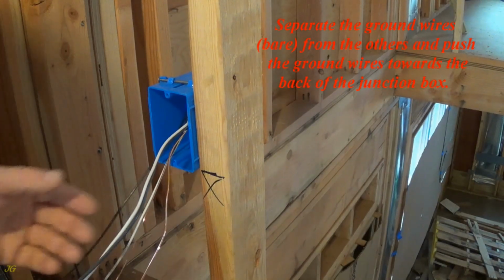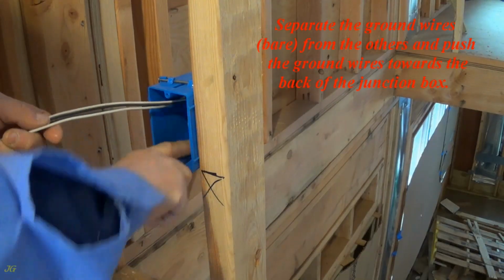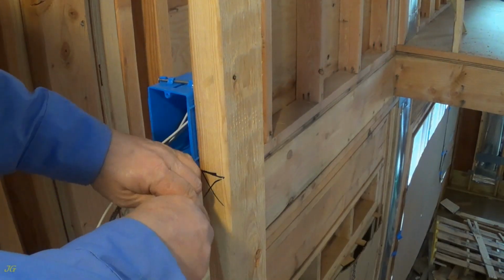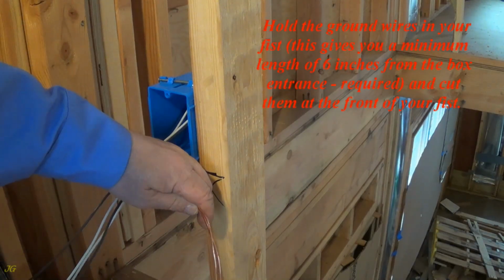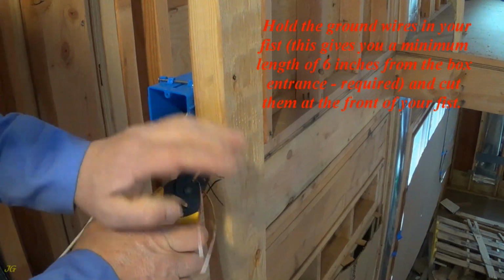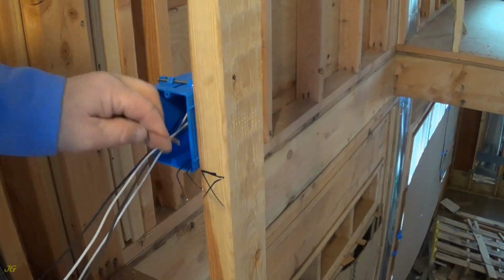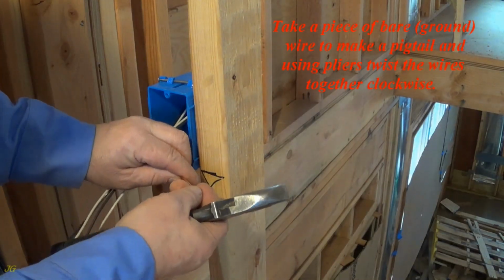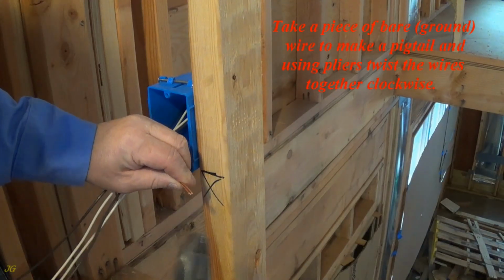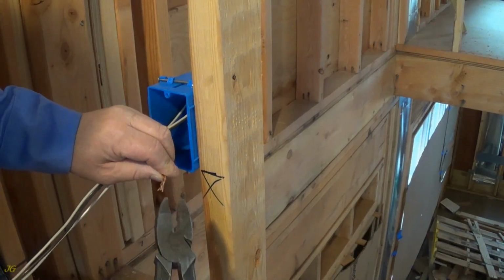Separate the ground wires, bare, from the others and push the ground wires towards the back of the junction box. Hold the ground wires in your fist. This gives you a minimum length of 6 inches from the box entrance required, and cut them at the front of your fist. Take a piece of bare ground wire to make a pigtail and using pliers twist the wires together clockwise.